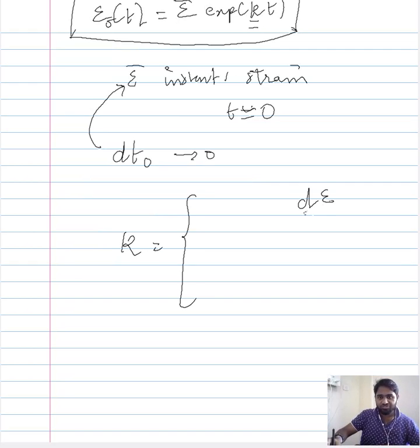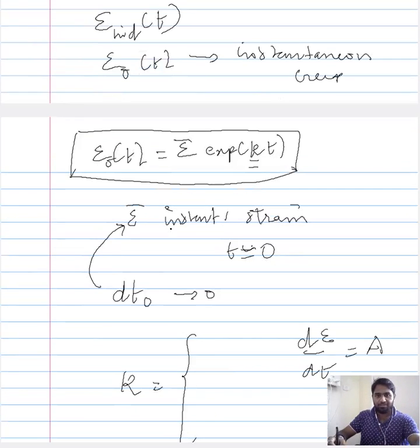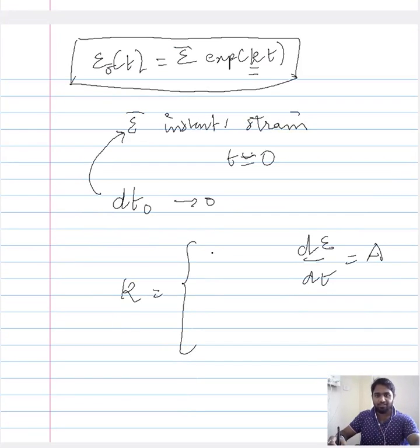And this term here is a constant term, and this term varies conditionally, meaning when you have a constant strain rate, as we have seen in the instantaneous creep region, then this prefactor here, that is K, is the change in the length of the material per unit length, meaning it is something similar to our description of strain.